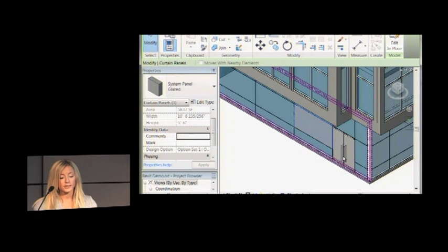The reason for this is that when you stack your walls, no matter how much you try, somewhere your center lines are not going to be completely perfect. So as you go up those 10 stories, they may actually be off ever so slightly, which will cause issues with your volume. And when you translate it through, you'll see that there might be gaps in the floor. And anytime there is a gap, you're adding more surfaces for analysis, and it has to fill it in, and it has to do these types of things.